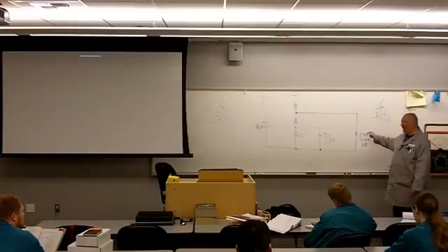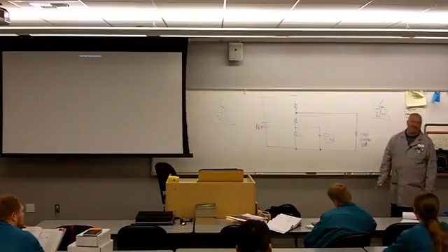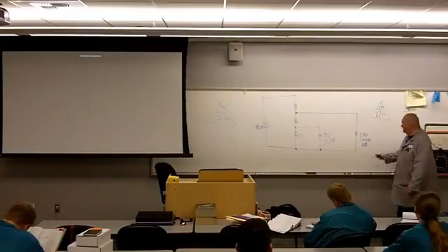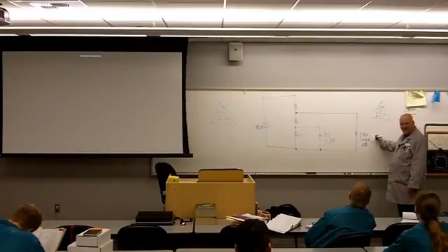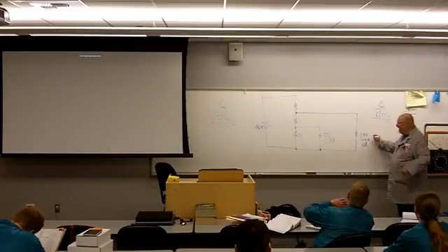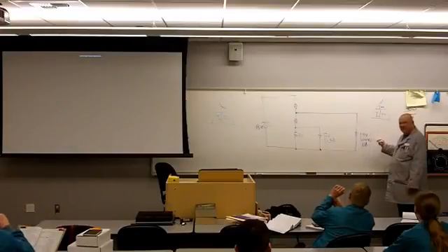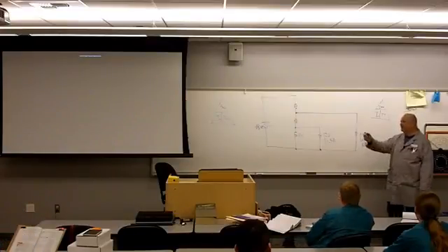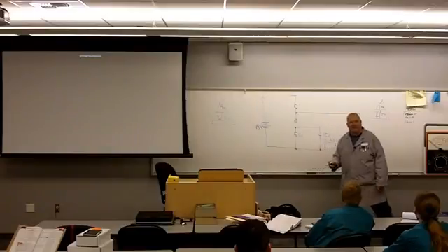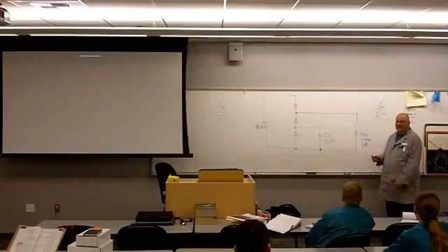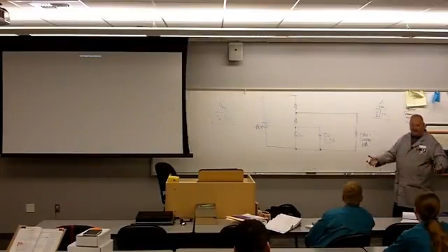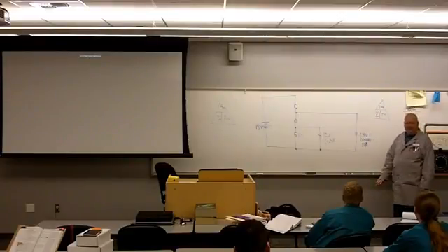And this might be what the placard data on the back of the radar says, or the manual says. Okay? But you understand which one of these are real. If you do the math, this number could be good, and if that's the case, then we know that the answer is going to be 8.33 amps. But in reality, because of the losses, because of the property of resistance, we're probably going to be consuming really about 10 amps. Make sense?